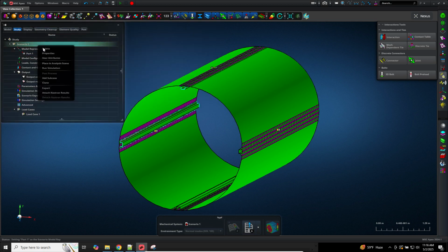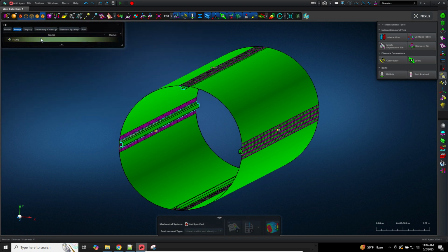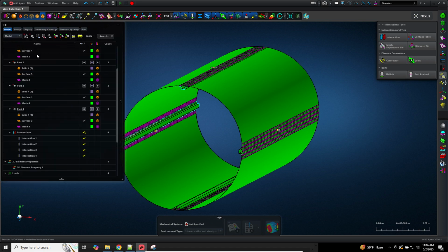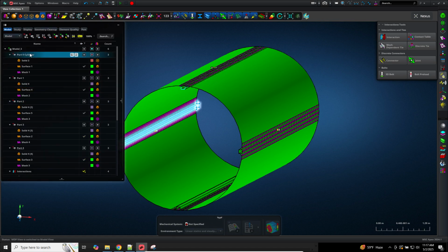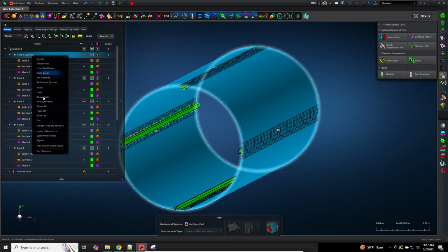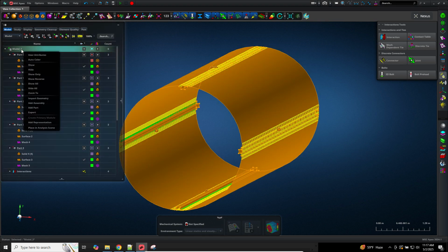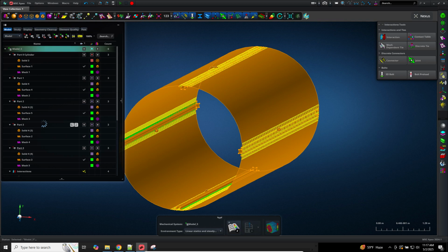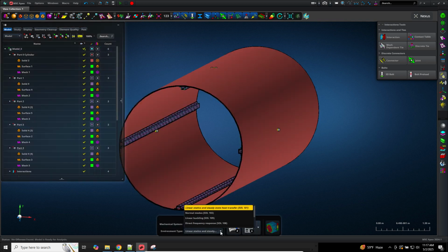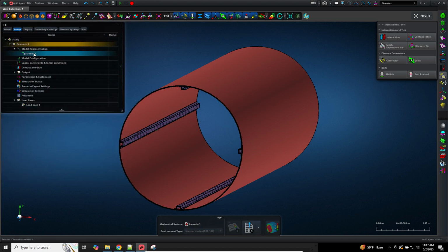Okay, so we have to delete the old study we created a moment ago. Before, what I did was the following. I right clicked on one part for the cylinder and then I clicked on place an analysis scene. Now what I'm going to do is say, you know what, take the entire assembly and place that in the analysis scene. Let's run a normal mode analysis. Click on generate a simulation scenario. So that was this button. And now we get a new study here, or a scenario.